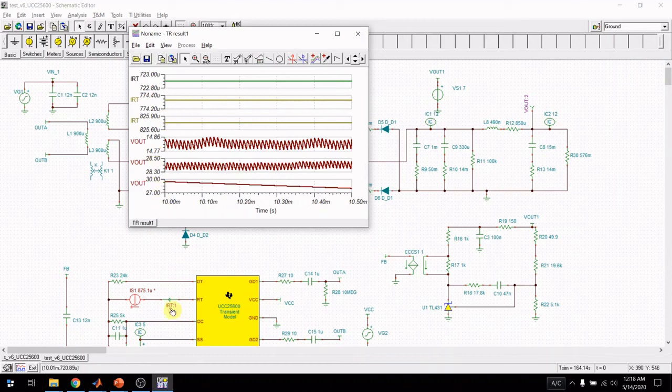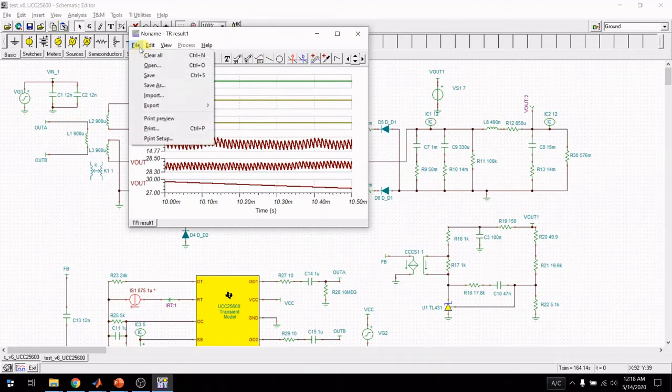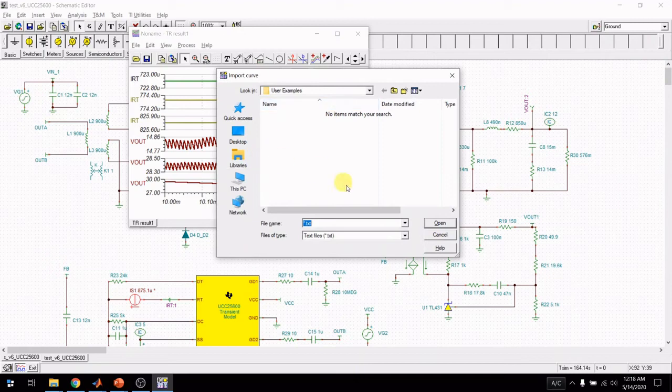So you can change the order of these by doing :1 and then :2 for output voltage. I also locked up the feedback, so it thinks it's always at 7 volts. That helps it start up a little bit quicker. But what you can do is, if you've got a bunch of these simulations, and I think I did like 40 points at a time, it takes about a minute each, you can export it to a text file.